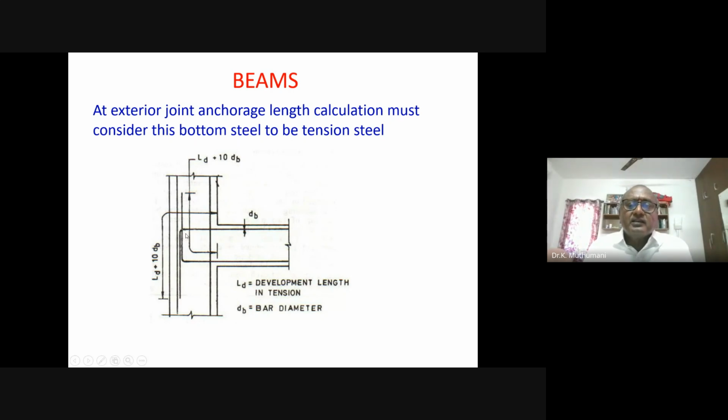Why I'm telling this about anchorage: whatever happens lately, maybe I can bend here, maybe I can bend here, still anchorage will be there. No, please don't take it like that. The joint strength, in terms of ductility, is very important. If the joint is kept weak, suppose you compute the length, and however, instead of keeping it like this, you bend it here, that kind of thing. You say that no, everything is designed because anchorage length depends on bond only, so it is fully bonded. Everything is fine. Please understand, it is not.